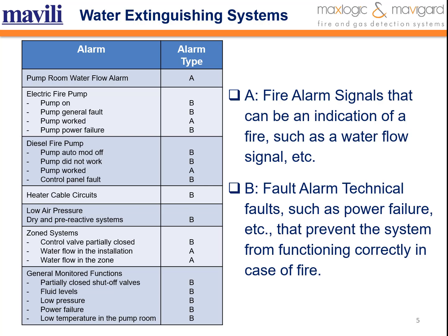Where the pump room is separate from the building, it may be impractical to provide sprinkler protection from the building's alarm valve sets. In case the sprinkler installation in the pump room is taken from the outlet of the pump with a stop valve and flow switch, water flow alarm information is provided from the flow switch.